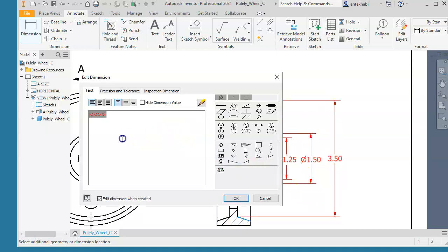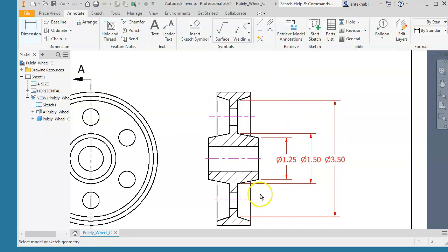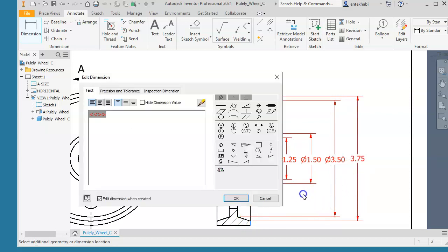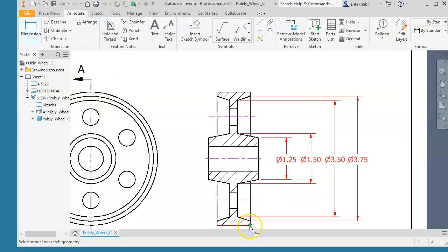Make sure it clearly reads as you're doing these dimensions. We can adjust it afterward to make it readable. That's the whole idea of the communication of drawings, to make it clear for the user. And these are something we are doing for manufacturing. Remember, always in dimensioning, think about the manufacturing process rather than just dimensioning the geometry. That's one of the basic rules we learned in the dimensioning chapter.